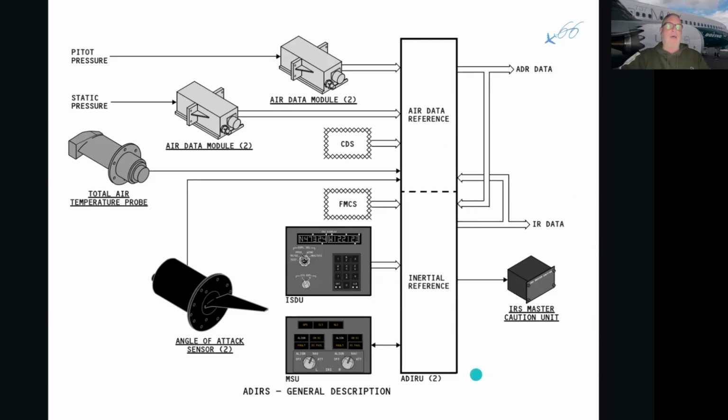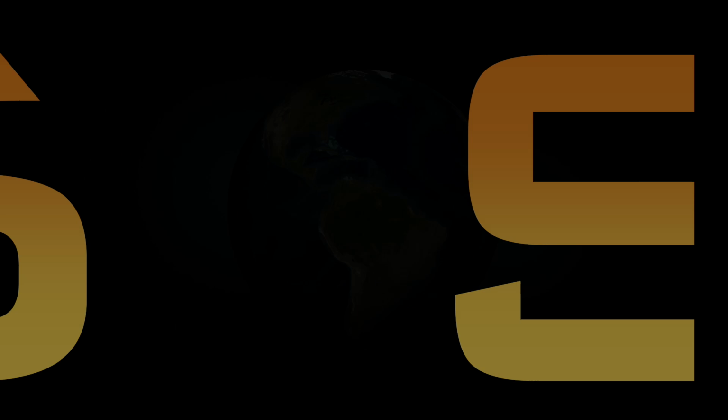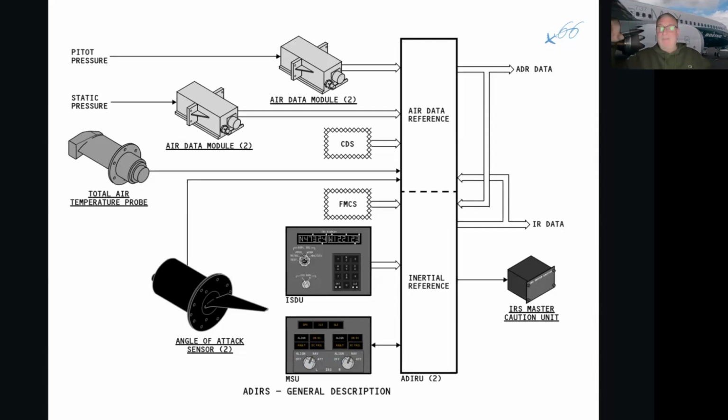In order to start it all up, I have to actually switch these on. So for ground operations, they're usually not on because, if you ever worked with or saw a gyroscope, or even an ADIRS nowadays, they come in a box. It usually says handle like eggs, even today. Even a laser gyro that has no moving parts still is treated as a very delicate object, a very delicate box.